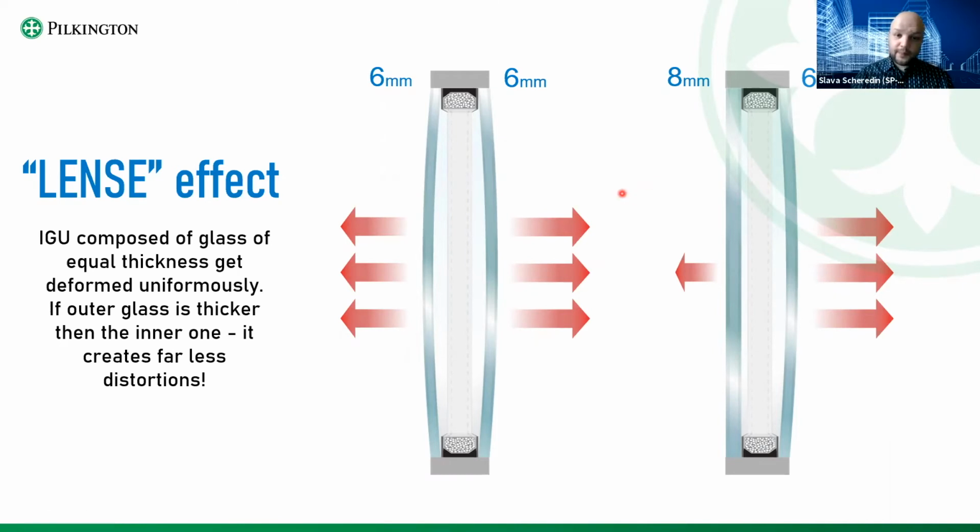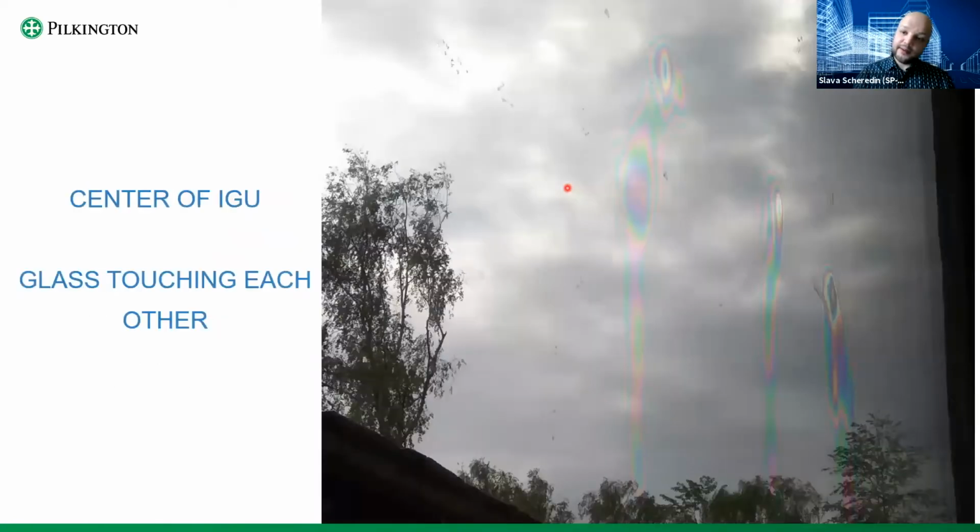But, okay, we've determined with the glass thickness, the general rule: the thicker the glass, the better. Always works, mind you. But if our spacer is too short, we may get the directly opposite effect in the winter.